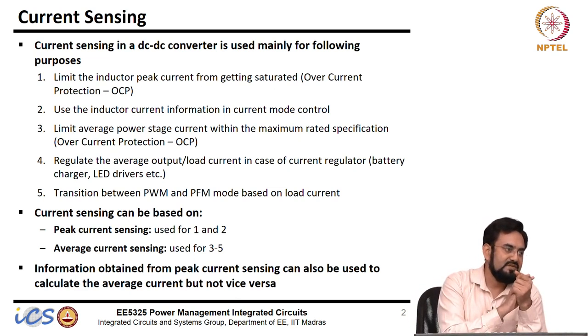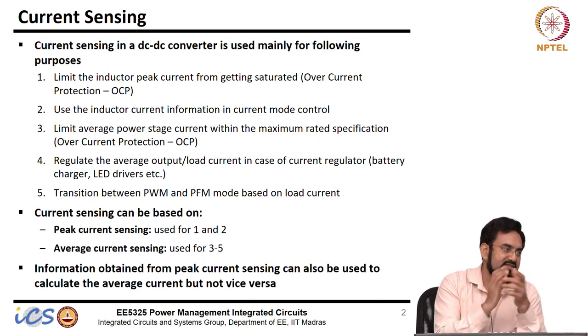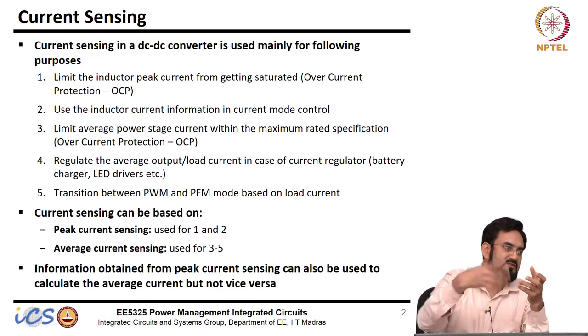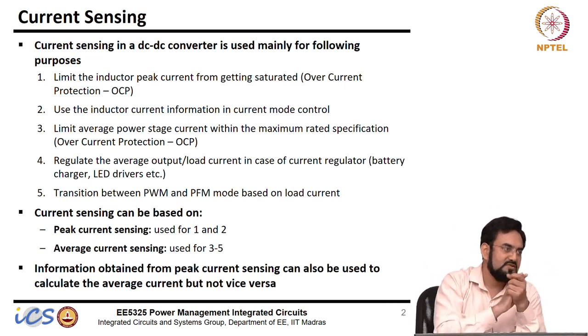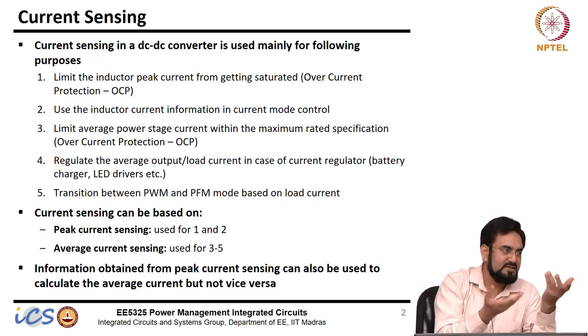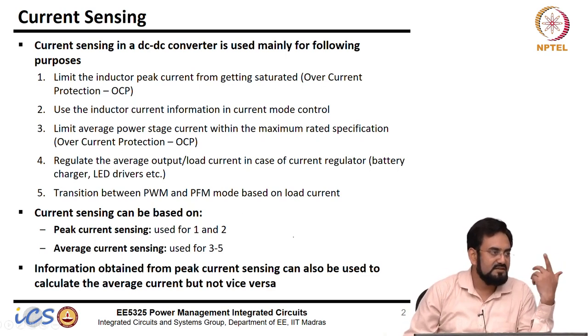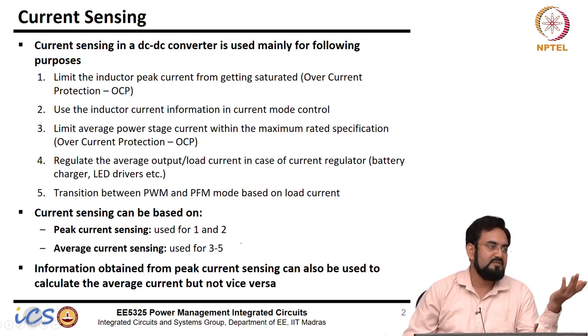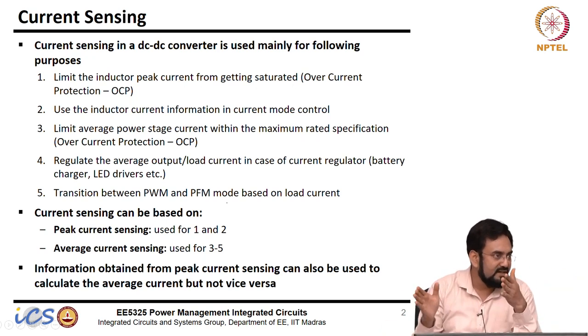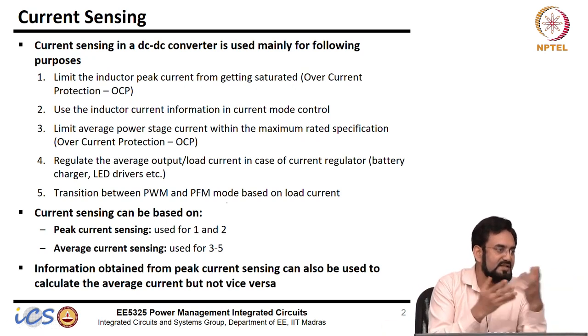With the help of zero cross detect, you can know when it's entering the DCM, because we need a zero cross detect to detect reverse current. The output of that zero cross comparator can always tell you when you are entering DCM mode, and you can enter PFM mode right away, or you can wait until your duty cycle is saturated, and that is also in your control.